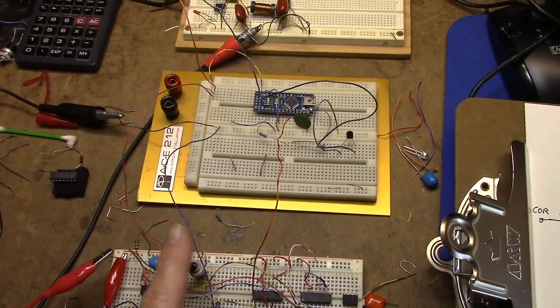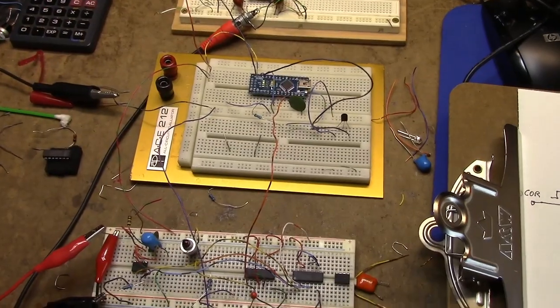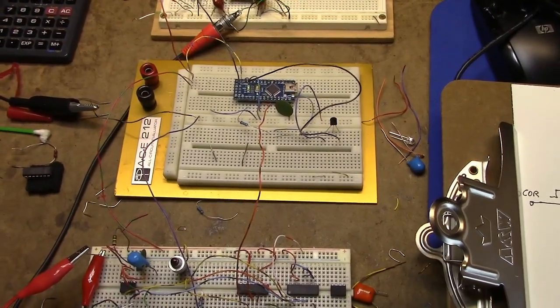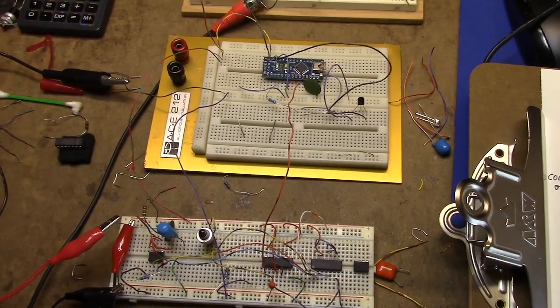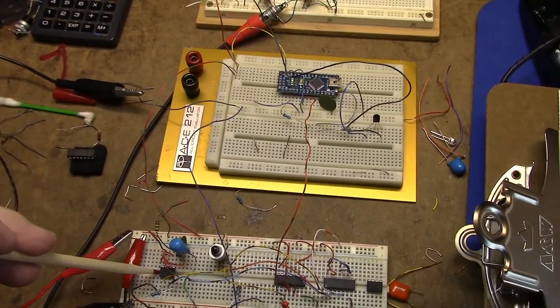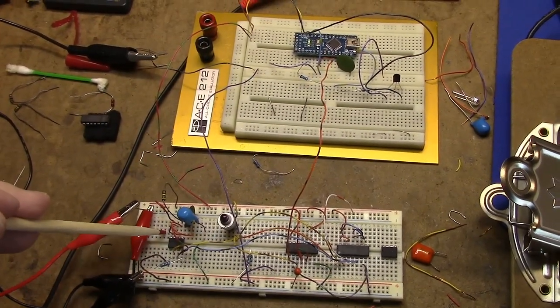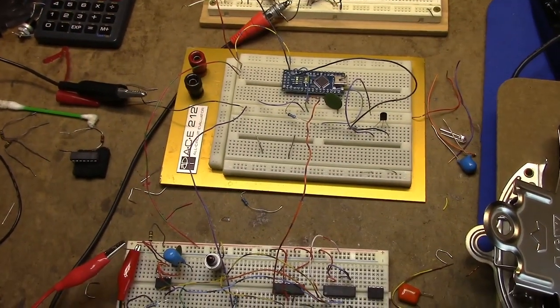But you can see here, as I keep triggering the transmitter, nothing happens because this is inhibiting it from transmitting again. And the purpose of that is I want it to ID every approximately 10 minutes. So this will inhibit the transmit for approximately 10 minutes. I may put a pot in here so I can set the timer on it. Anyway, that's basically how the circuit works.